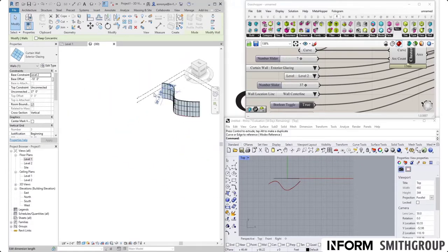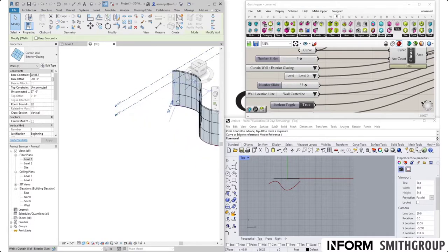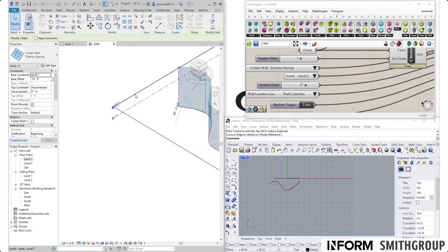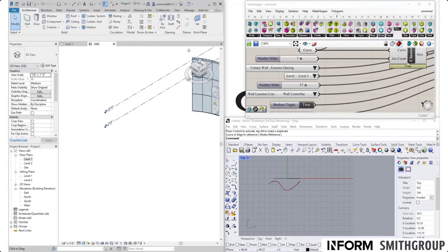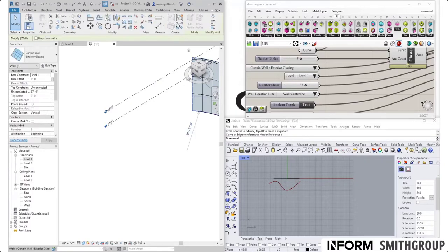So the levels don't necessarily mean that the base of the wall would move up to that level. The wall actually stays where it is. The levels also stay where they are, but what changes is the base offset. So that's something to also take note of. It's not like nothing changed, except from the fact that you have the base offset as 0 now.